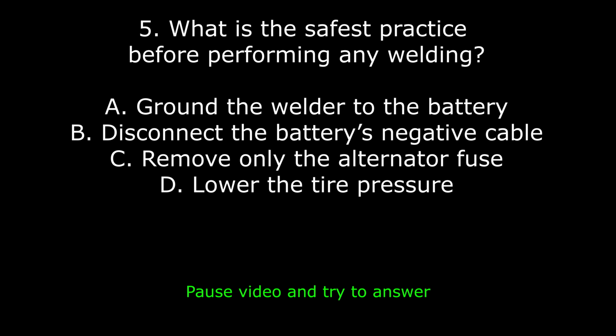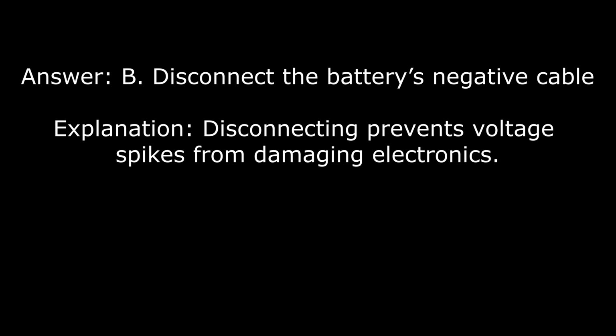5. What is the safest practice before performing any welding? A. Ground the welder to the battery. B. Disconnect the battery's negative cable. C. Remove only the alternator fuse. D. Lower the tire pressure. Answer: B. Disconnect the battery's negative cable. Explanation: disconnecting prevents voltage spikes from damaging electronics.